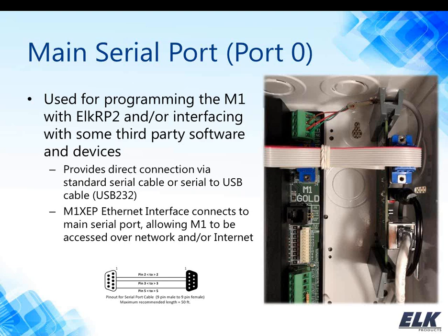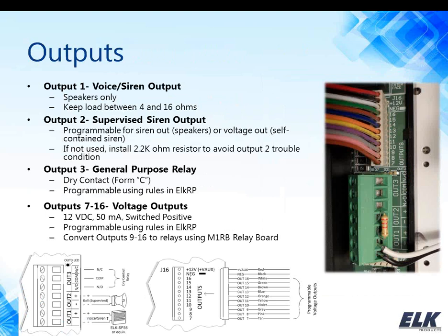You can also program this thing through that main serial port as long as you have a USB to 232 type cable or a straight 232 cable itself, and you can see there is a little wiring diagram underneath all the wording. The downside of that is there's hardly any more laptop computers that come with a 232 port in them anymore. Fortunately, we do offer a USB to serial cable that is tested and proven to work with the M1. That part number is ELK USB 232, so if you need a cable to connect directly to the M1, grab one of those. Now, if you have a USB to serial cable, it may work. You should try it, but they're not all compatible, so just keep that in mind.